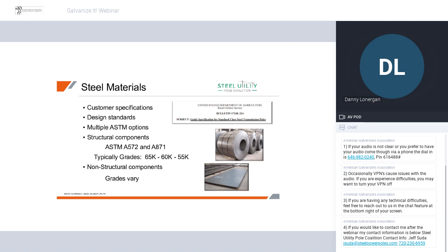I have a clip in here of that spec. It's a bulletin. We typically refer to it as the 214 bulletin, and it's important that you know it's a 214 because it's written specifically for class poles, if you will, and or standard poles. It walks through everything you would expect to see in a specification. The key to the 214 is it has a sister document, the 204, that is pointed at custom structures.